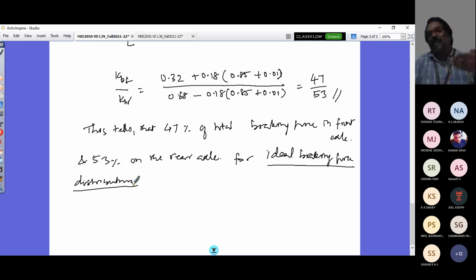The wheels which are locked at the rear axle cannot support or resist the smallest side force that can be induced due to a wind gust, or maybe the road camber, or maybe by the centrifugal force itself. So it cannot support the necessary lateral force requirement, and that would be drifting out, and then the entire vehicle would have a yaw motion with respect to a yaw center in the front axle.